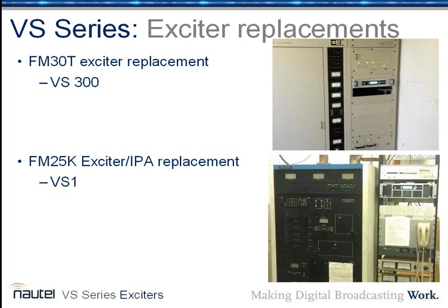Okay, great. Very good. And on the caveats and catches, I believe when you were doing this, you did have a couple of timing issues with the muting? Timing is everything, as they say. The biggest problem we ran into was that the Harris likes to go into a recycle state on low RF drive because it assumes there's something wrong with the exciter or the IPAs.